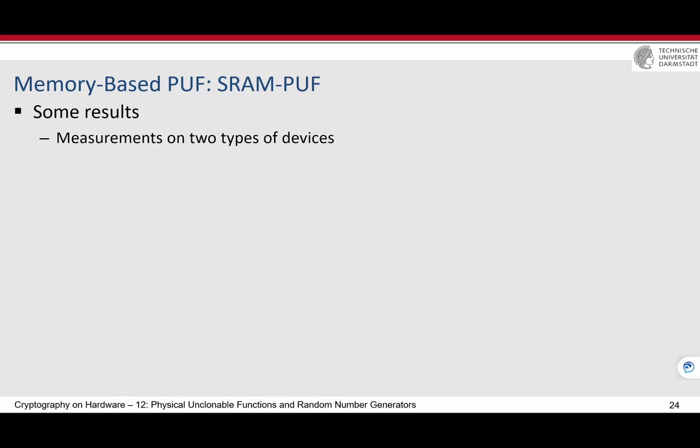And then if you build a pattern where you intentionally violate the requirements, it's not predictable which lines will be connected to the other one, and it depends on the process variation. Based on that, some kind of PUFs are generated inside the chip, which is completely challenge independent, but completely fixed. And most of the time, they are also somehow reliable. It doesn't matter how many times you read this value from these two lines, I mean, always they are either connected or not connected through the process variation.